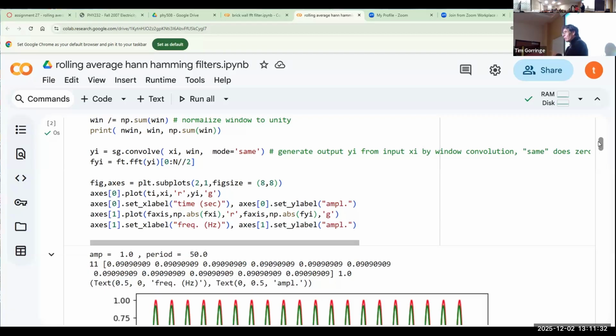But what happens when I'm at the very first sample, or at the very last sample in the array? I'm at sample 0 in my signal array, and I want to convolve it with my 11 sample window. The center of the window will be set at sample 0, so I'll include that in my weight.